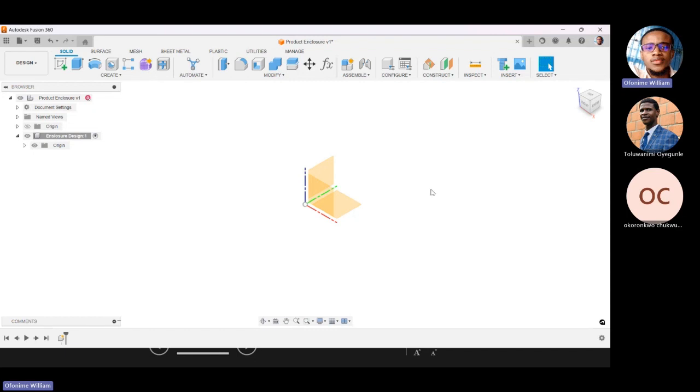If you're looking at something for mechanical application, probably we try this. For instance, we have the PLA, and the PLA you saw there already has a lot of variation. There's PLA plus, there's PLA tough, there's PLA normal. The PETG you saw there, the G is like an upgraded form of the PET plastic. We have other ones like ABS. We have other ones like nylon, and the waterproof ones. We have CPE. Now we are looking at use cases like buildings, some form of structural stuff. And there are so many of them.